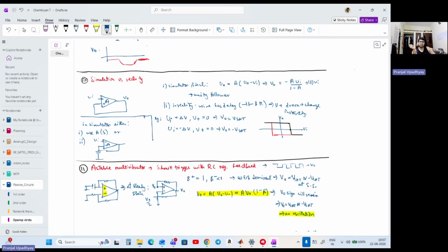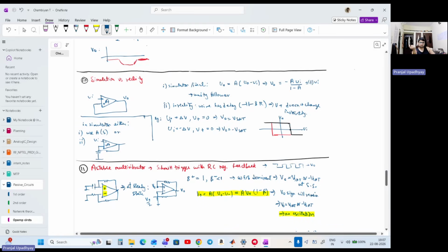So a good design practice is that when doing simulations at the design level, transistor level, or system level, we try to add some parasitics and resistances on our own, which account for all the parasitics which will happen in the layout process. Cool. Now, let us also discuss what will happen in reality.